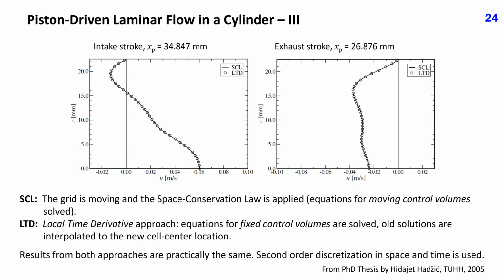Results from both approaches are practically the same. There are no obvious advantages of one approach over the other in this test case. However, LTD approach is attractive for simulations in which the grid needs to be regenerated from time to time, as the grid quality may deteriorate considerably when the same grid topology is kept all the time during motion of bodies relative to each other.